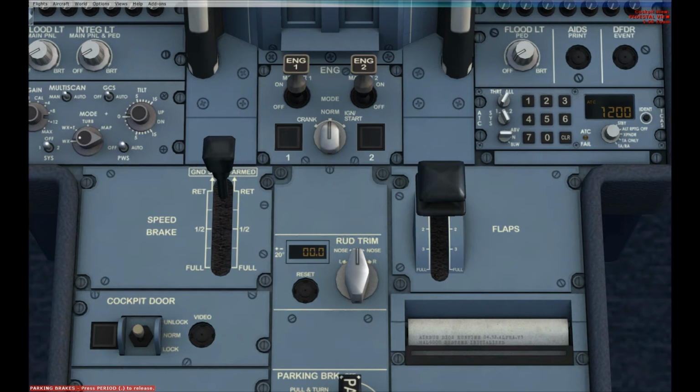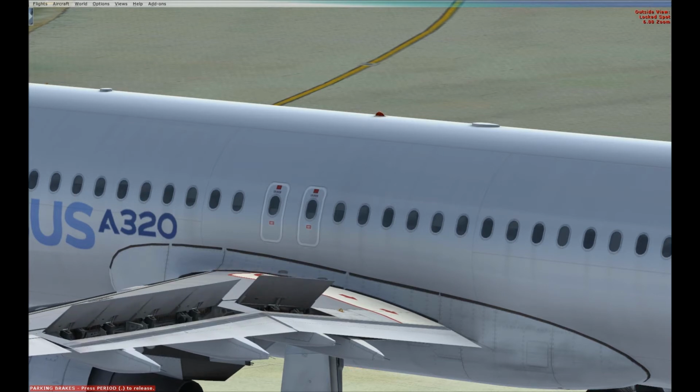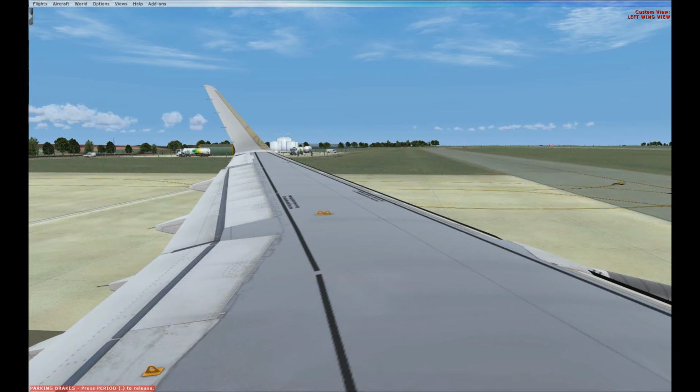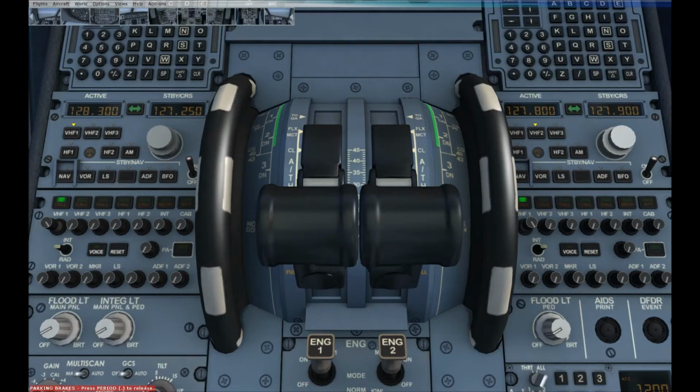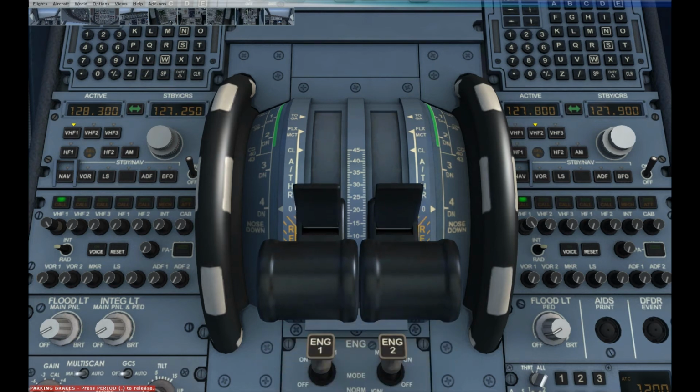The speed brake can be set in full or in part as required depending on the flight parameters at the time. So it could be a quarter or half or 3/4 or full. This is reverse thrust being set once again. The flick levers pulled up, the throttle levers fully back, and then back to idle.